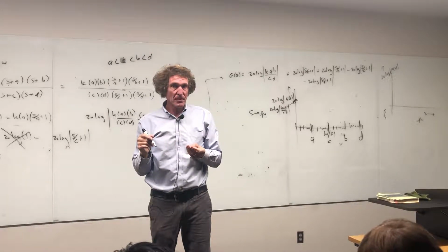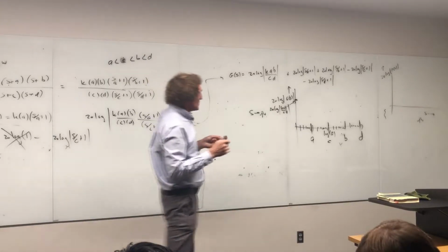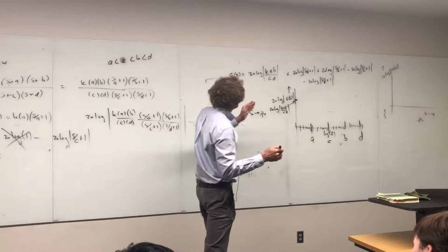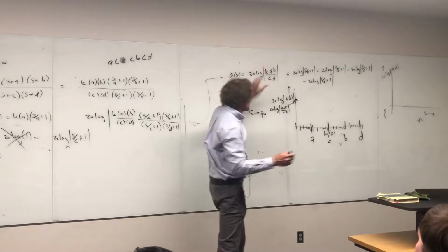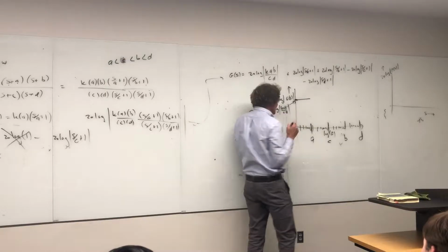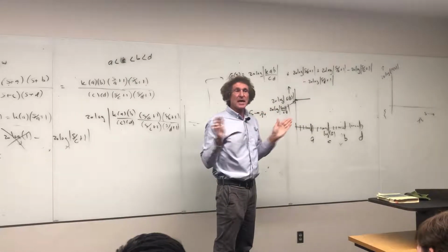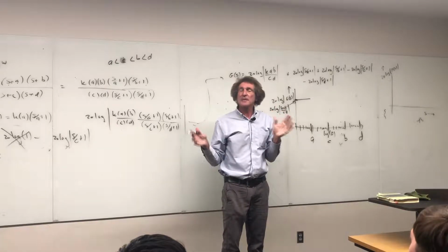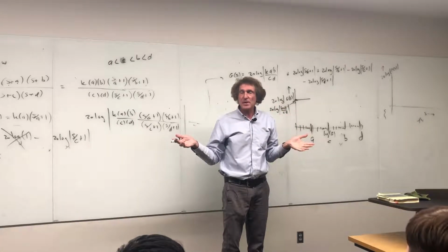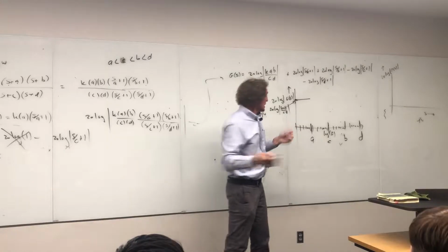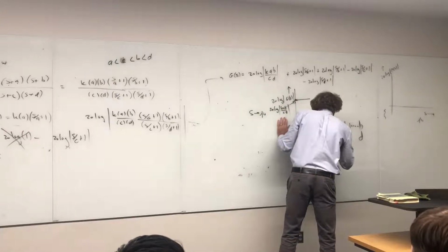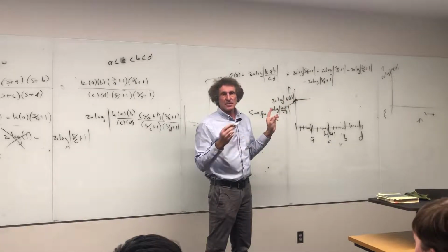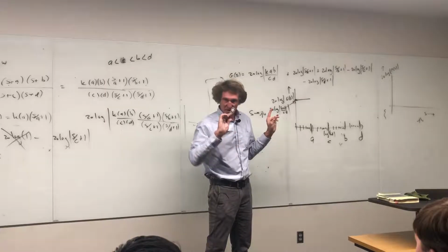Everybody okay on this? Remember to do what I'm showing you on this. So now this thing starts here, whatever that value is, right? As soon as it starts, it's going to stay at that value until I hit A. Do you follow me? It doesn't change until all of a sudden S over A equals 1 in magnitude. And S is J omega, right? So it's really omega over A equals 1. Let me plot not log of F, but log of omega. That way it'll be easier, because I'd have to take the 2 pi into account here. I just want to plot just omega, okay?